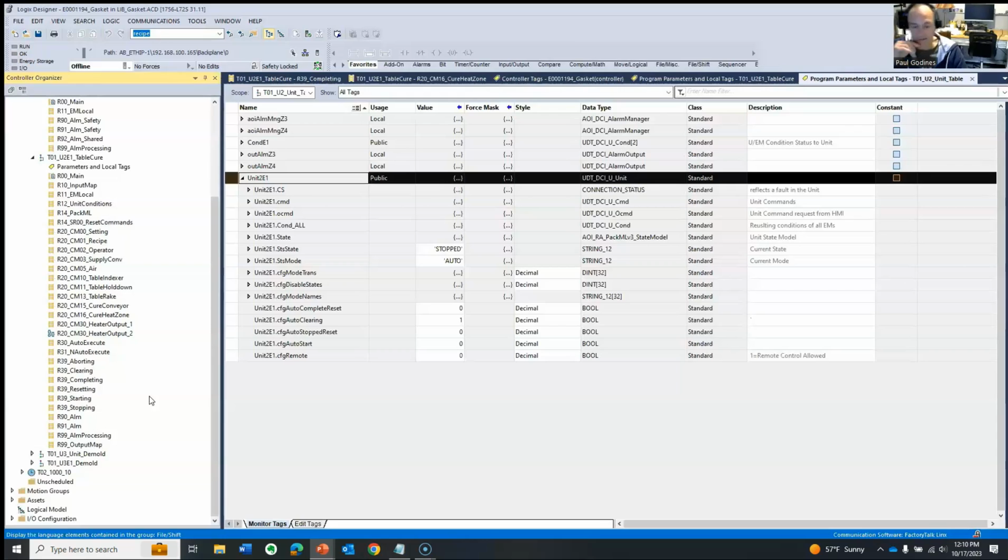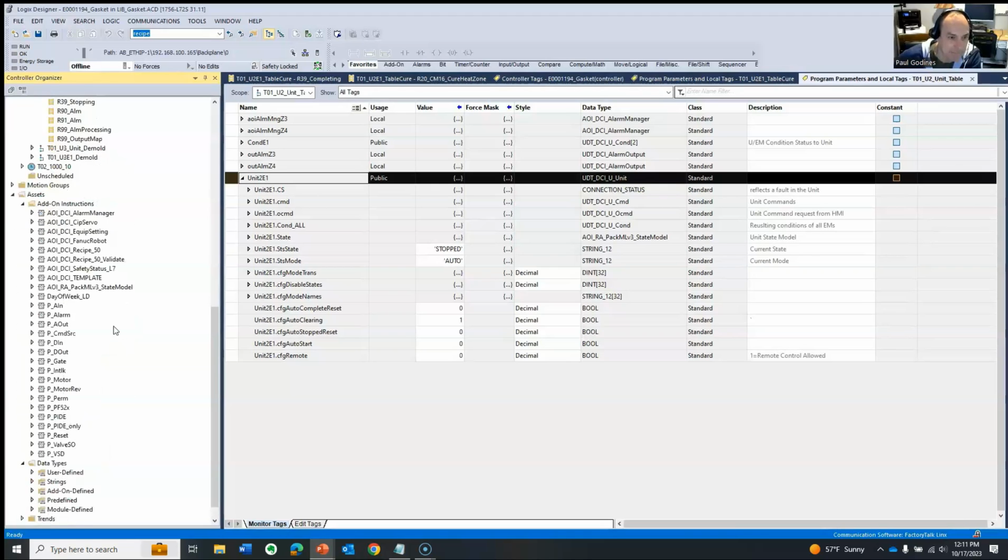So all the tags that are referenced to that device. Say I have a camera or some sort of safety device. All the tags associated with that can be put into a UDT. Therefore, when I need to find those tags that are associated with that device, I go to my UDT, and all the tags I need to reference, in all the different types of tag structures that I need, are all in one compact place, a UDT. That's what I refer to them as, sort of my filing cabinet, right?